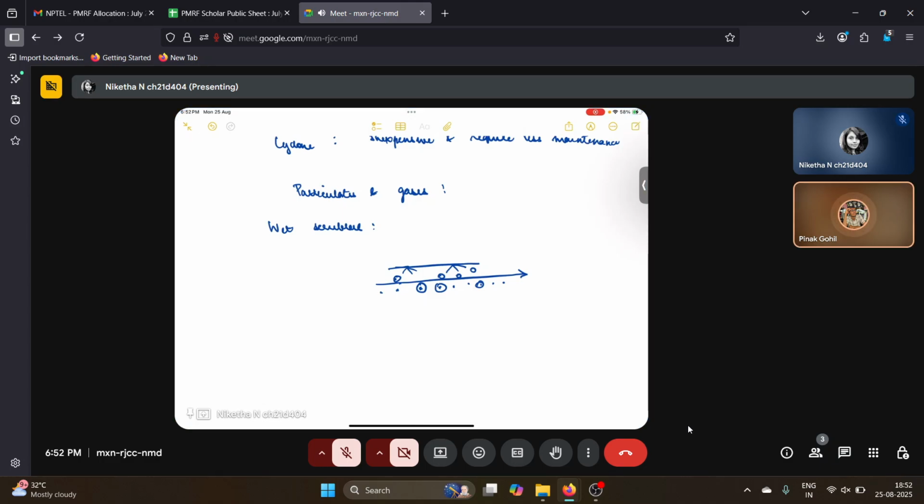When you have water particles stuck with the particulate pollutants, the weight tends to increase and it will fall down along with the water. Then it will be collected at the bottom as slurry. Why slurry? Because it is a combination of solids and water, a mixture of both.